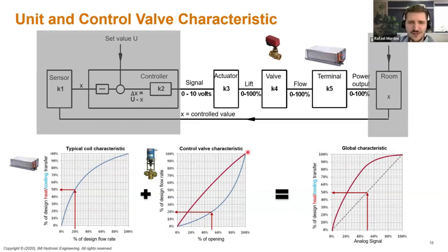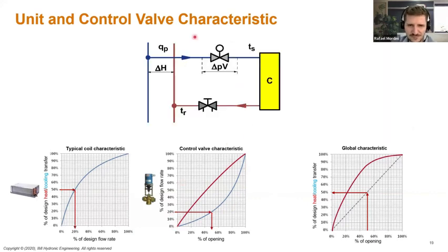The control valve that originally has this curve here will have its curve deformed. And this happens because of variation of pressure. This happens when the valve is closing on its circuit. You know, your whole system is fully open and you decide to close just one valve. When you close this valve, you close like 50%, 20%, you already start to deform its curve.